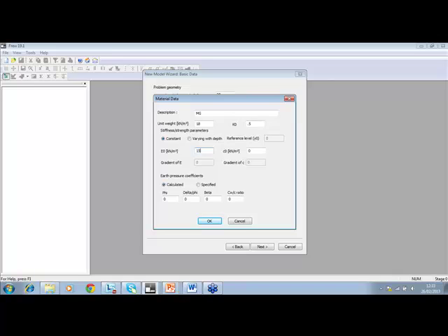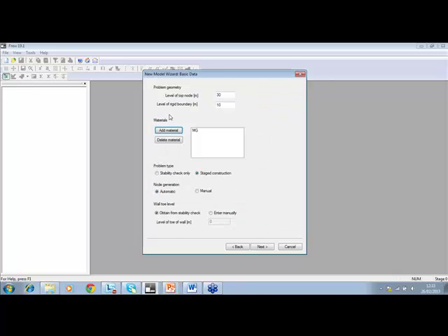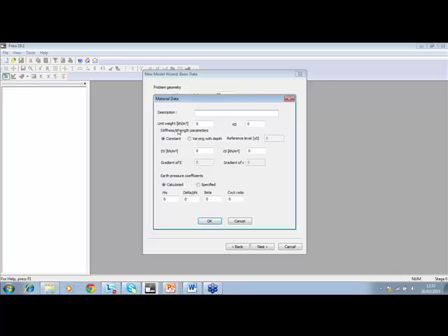Okay, so we've got 15,000 for the Young's modulus. It's a drained analysis, so no C0. I'm going to specify our K values, so 0.29, 4.5, 1. For soil structure interaction analysis, the KR value is important, and it isn't inputted here. So this is for glacial till, and I'm inputting this now.